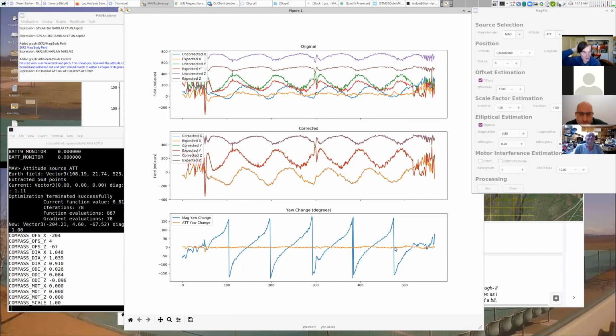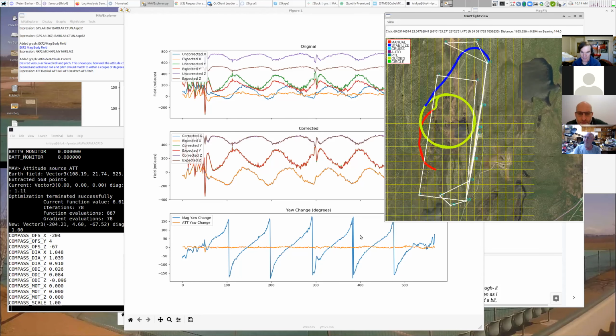And in fact, putting in these values would not have affected his flight very much, except in the first little bit before the EKF had learnt them, right? The runway takeoff could be a bit odd, because the EKF can only learn the values once it's got some movement, right? But for most of the flight, certainly this up and away flight, it wouldn't have made much difference.